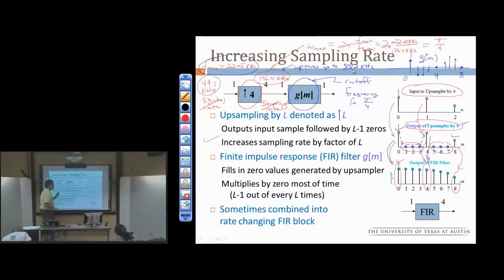So the good news is, from a data converter point of view, it gives me all these frequencies to put quantization noise in that I can't hear. And later I'll just low-pass filter them away. Kind of fun. And for other reasons, we just need to match sampling rates. We need to match it to a target sampling rate.